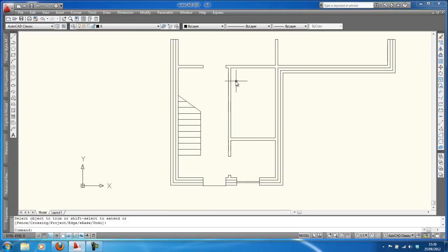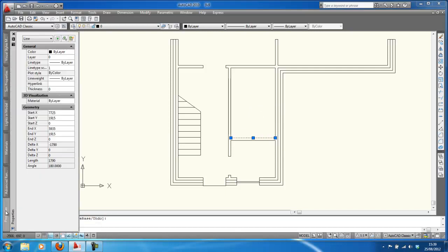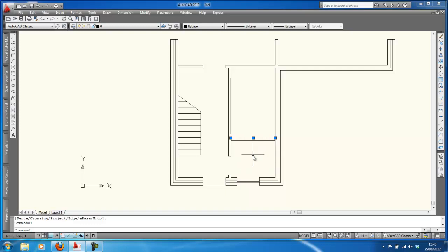Now the next process is to decide what you're going to use this for, as whatever room. You can use it as a very narrow kitchen, because really the width here, okay, you can go to dimension to find the width, but if you click on that line and then just touch properties, can you see it tells you that the length of that line is 1790, so it's almost 8 foot wide. So really that can be your kitchen, because if you're arranging this as a cloakroom toilet, keep the wet areas close together and keep them to that end.